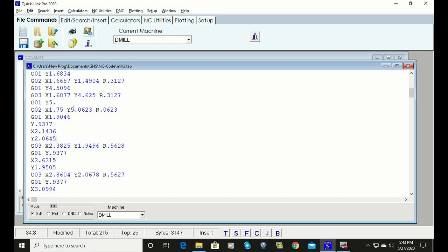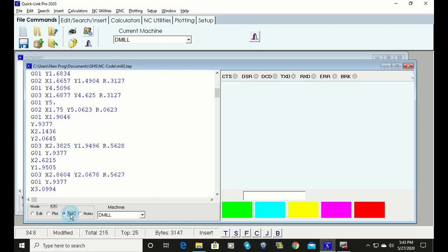Okay, so going to DNC is no more than just turning on DNC in that machine and hitting send. Okay. Once this has all been set up by the machine name, it knows which port to go to. It can deal with all kinds of multi-port devices, be they network devices or local USB switches, USB hubs with different ports on them.